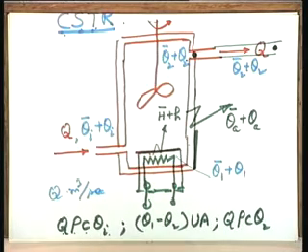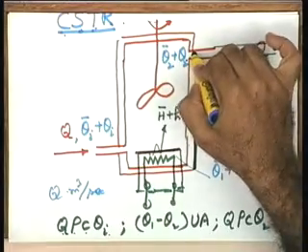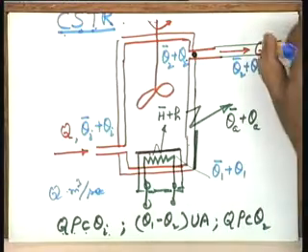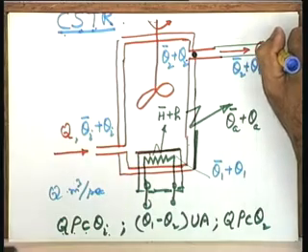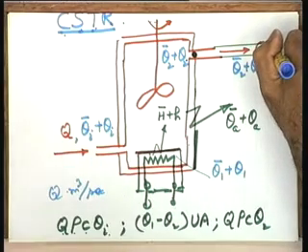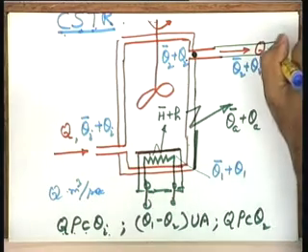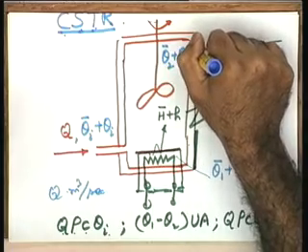Anything that is happening to the system is unknown to you. The variable which you are sensing and feeding back in the control loop, as far as the controller is concerned, the controller does not have any information at this particular point. The controller has information of the temperature at this point only. So the controller is intelligent with respect to this information and not with respect to this information.